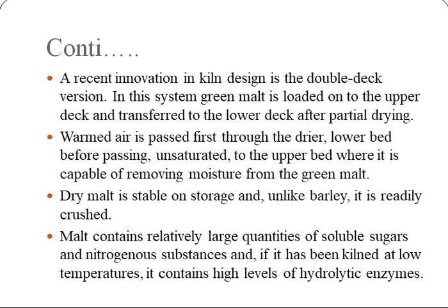So warmed air is passed first through the dry lower bed before passing unsaturated to the upper bed, where it is capable of removing moisture from the green malt. So green malt moves from the upper deck to the lower deck, but the warm air moves from the lower portion to the upper portion. So it removes the moisture from the green malt.